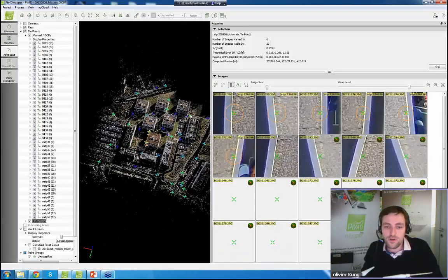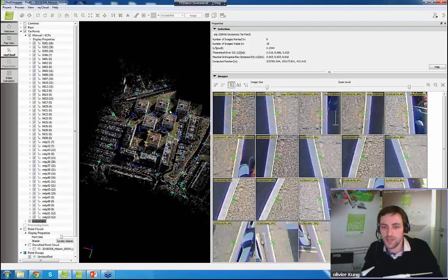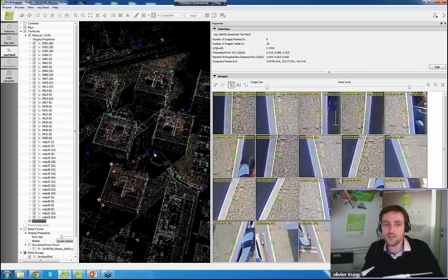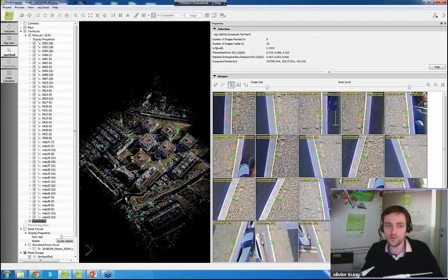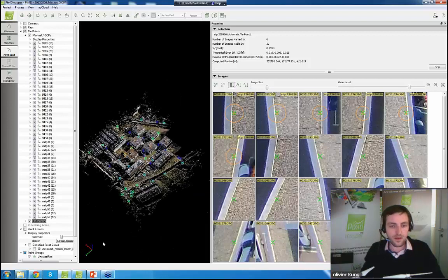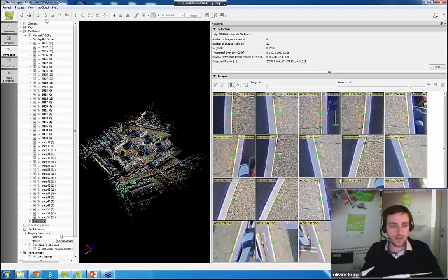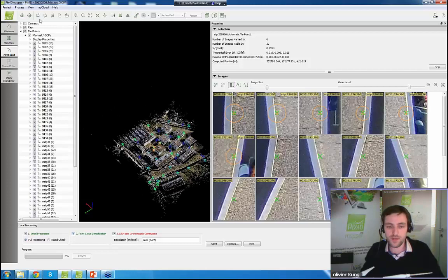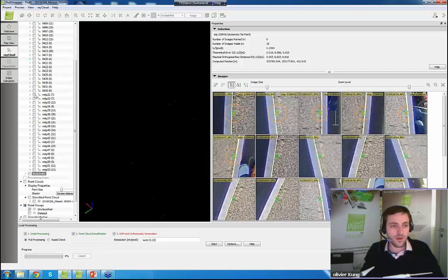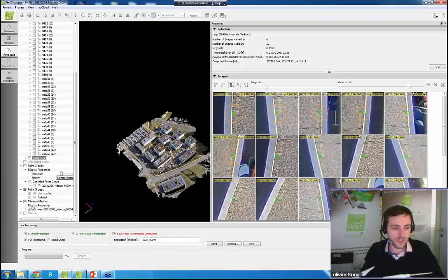So for a typical project done with the DJI Capture app, maybe something that sounds reasonable is to add anywhere between, well, 0 of course, but 5 to 10 points. That usually is plenty enough to make sure that the whole thing is really well calibrated. So you don't have to do it, but if you do it, there's a chance that you improve the quality of the results. And after that, you can regenerate the step 2 of the processing that includes the point cloud and the mesh. So let's display again the mesh and the point cloud.